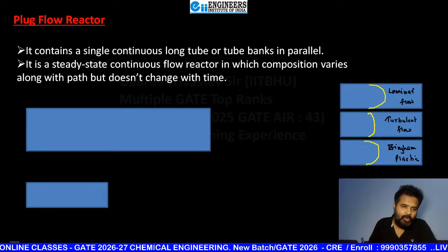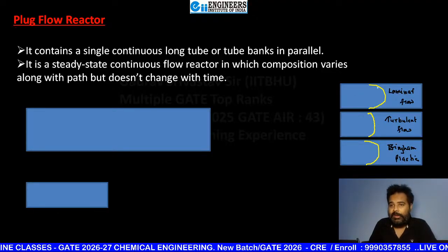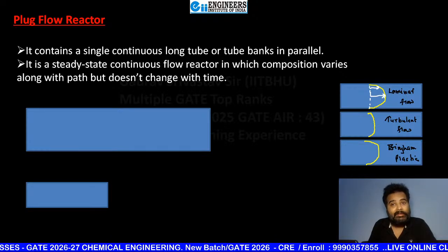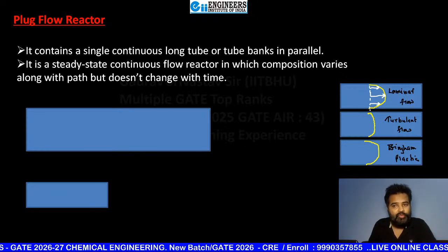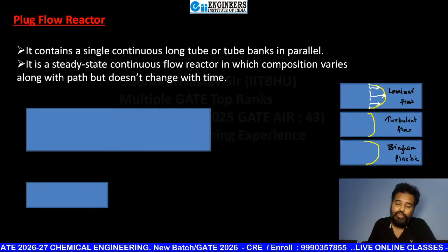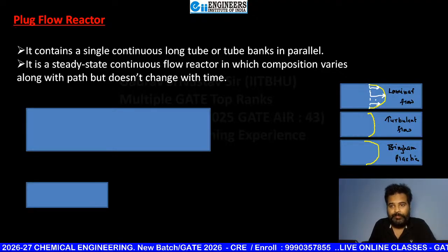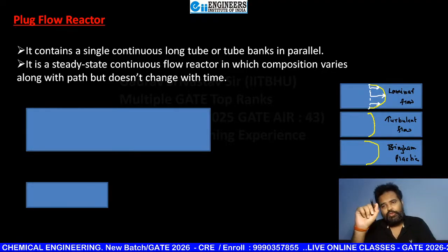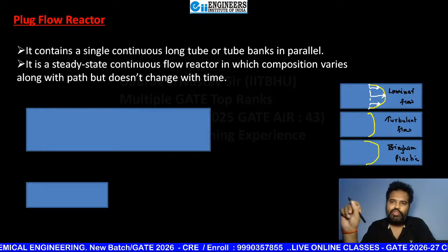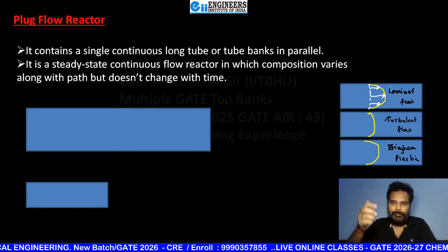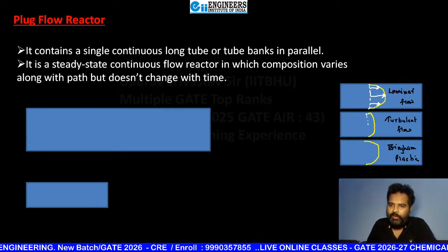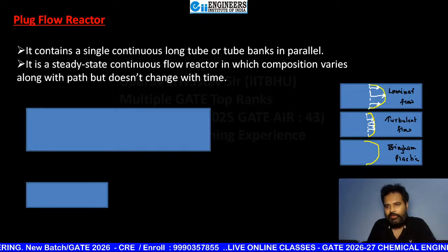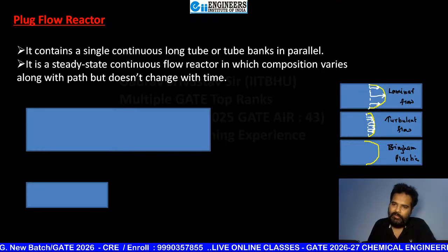Okay. Now just focus here. Clearly you can see the magnitude of velocity is maximum at the center, and when you go towards the wall, velocity decreases, and at the wall velocity is 0. That is the no slip condition. If the wall is stationary, the velocity is 0. If the wall is moving, then the fluid velocity is equal to the velocity of that wall, because of the no slip condition. In turbulent flow, you can see mostly near the center a flat profile.